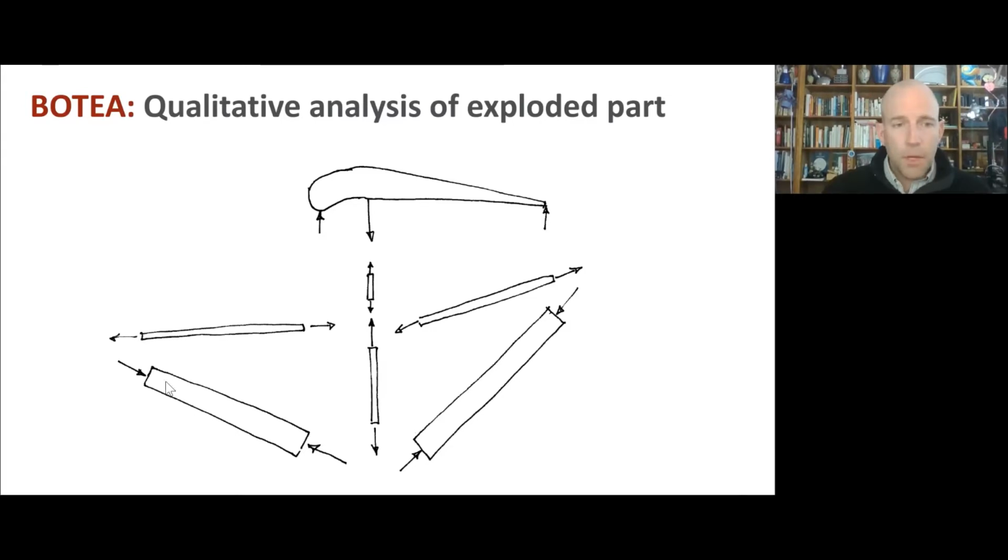We have those same compression and tensile elements that we talked about before to create that moment to support those endpoint loads. And then in the middle, we have these skinny little straps to hold things together. We need to apply this downwards force here, and that is going to be really transmitted down all the way to these bottom elements.